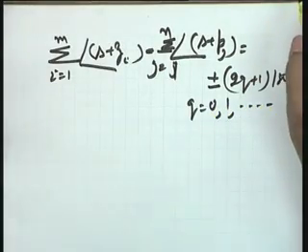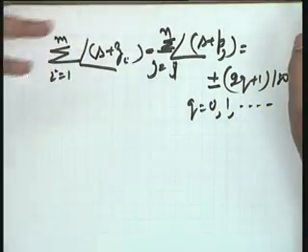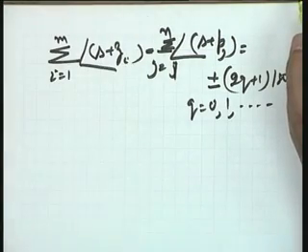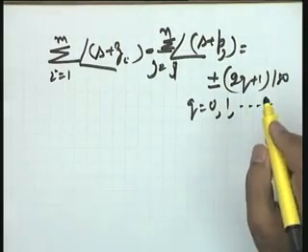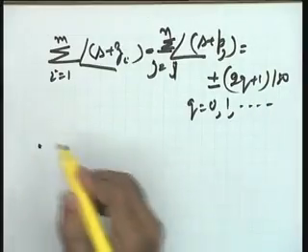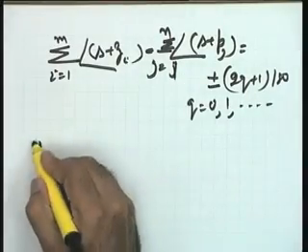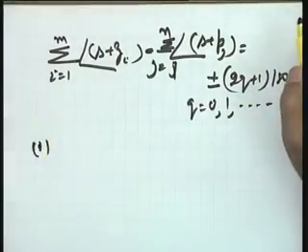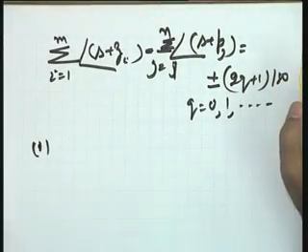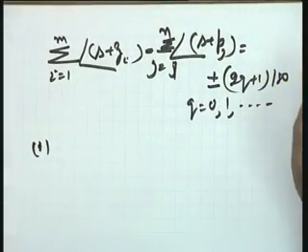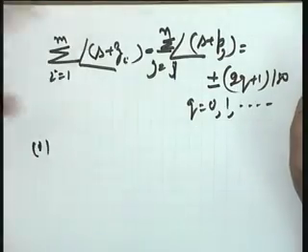This is your angle condition, and you have told me last time that the magnitude condition is satisfied by any point in the S plane. So our modus operandi is going to be like this. Number 1, scan the total S plane where the angle condition is satisfied. Look at this point please. Scan the total S plane where the angle condition is satisfied. Join all those points with suitable graphs, suitable lines. Those are the root locus branches.